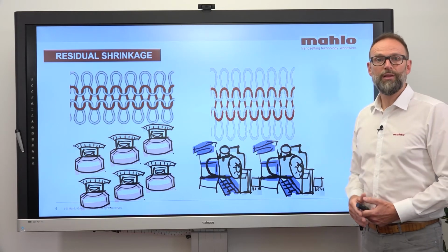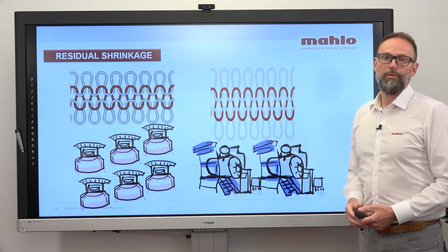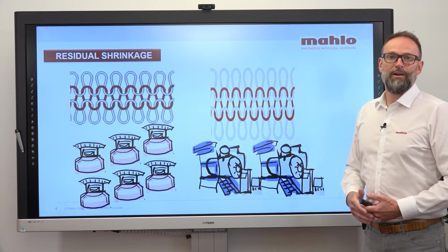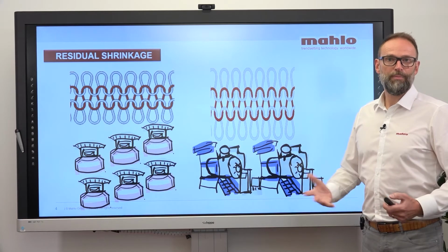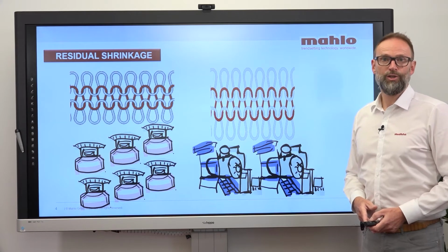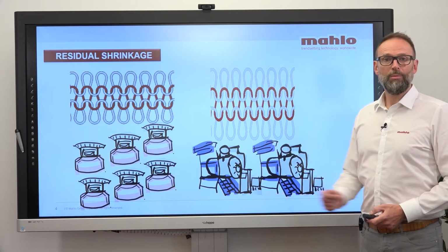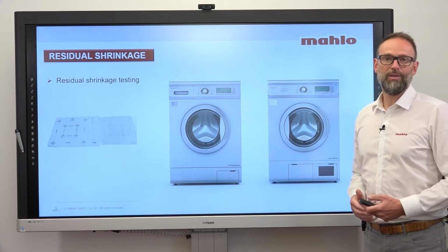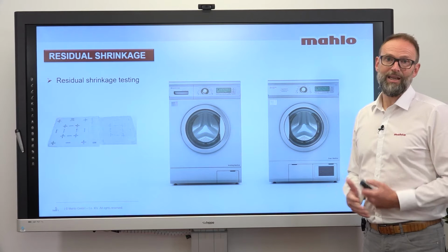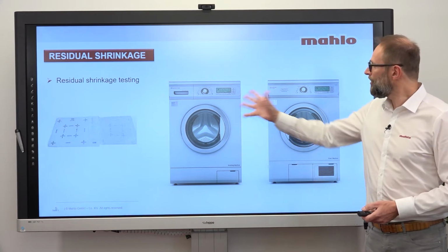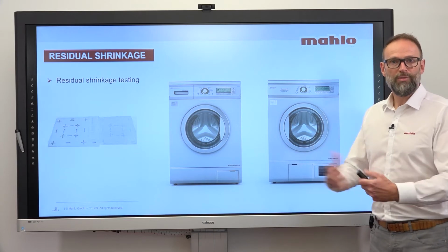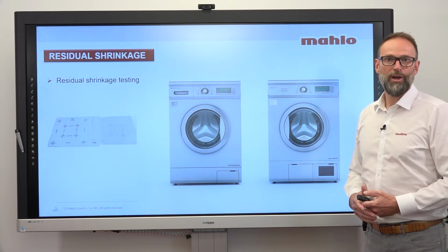Some of them treat the fabric with a lot of gentle and soft movements, but other operators treat the fabric with a lot of physical force and therefore apply a lot of tension to the fabric. Normally, to see whether this tension is too much and the density has been affected too much, we do tests with a washing machine and a tumbler to see whether the fabric is still meeting the requirements.